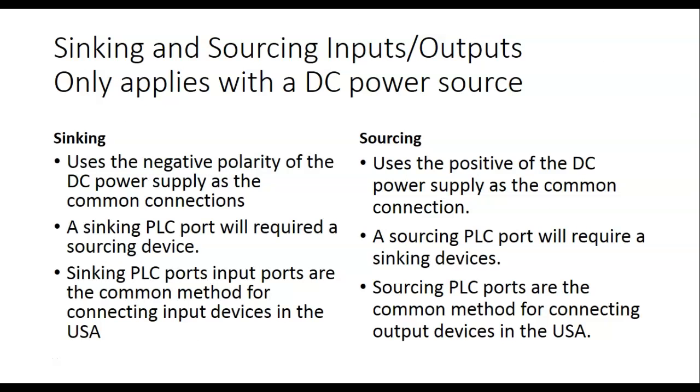Some things I think we already talked about, sinking and sourcing, in this class, right? Sinking uses the negative polarity of the DC power supply as a common connection. A sinking PLC port will require a sourcing device. Sinking PLC input ports are the most commonly used here in the USA. So all the PLCs that we have are either configured to sink or they're sinking by default.